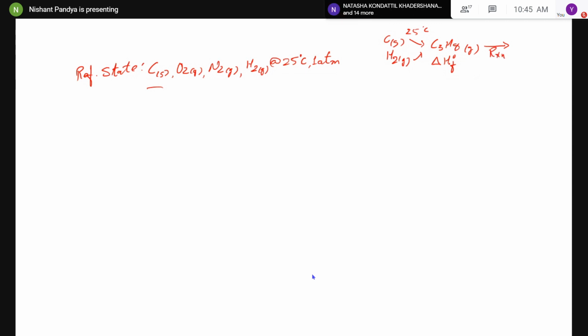What we do is, we take the reactants and the products produced here, CO2 and H2O, and calculate their enthalpy with respect to the elements, not with respect to the reaction. So we take the elements as a reference state and find the enthalpy. Now we have the enthalpy of all the reactants and of the products with respect to elements. Then we take the difference, product minus reactant, which gives the enthalpy change, including temperature change and reaction.